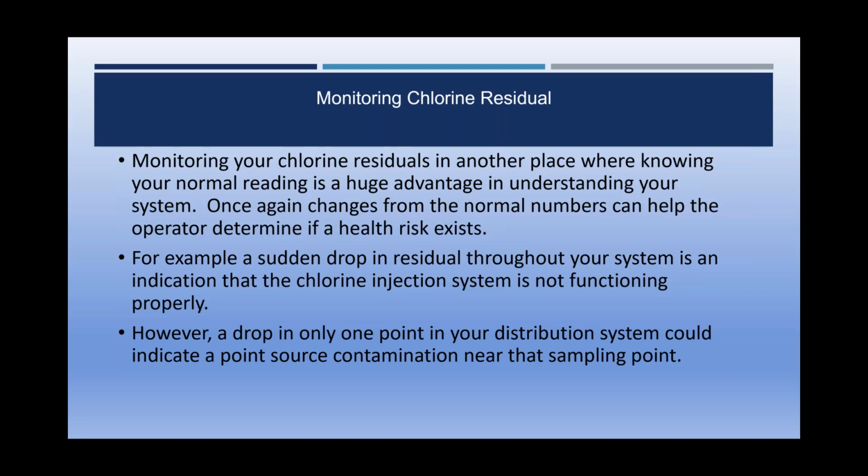And if you're not getting enough, then you slowly increase the amount of chlorine you're putting into the water, and you monitor that over time, and hopefully you will slowly build up to the right number. But of course, you don't just test one place. You test several places within the community, as well as testing in the treatment plant itself to make sure you're putting in a known amount. And of course, once the system is tuned and running,